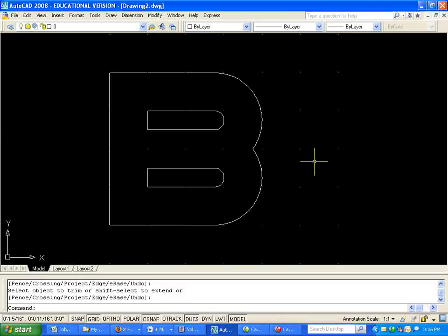Once your assignment is complete, you're at the assessment phase. And as indicated in class, I will assess or grade your projects based upon how well they match my required objective. To do so, we use a command called pedit. Pedit is what modifies what's referred to as a polyline. A polyline is a linear element or curved element with multiple vertices.